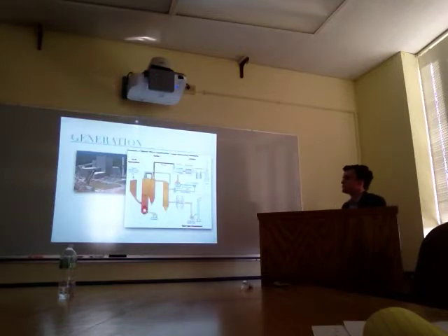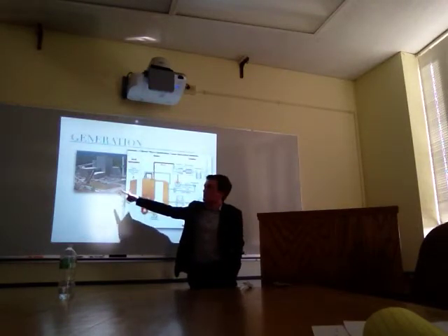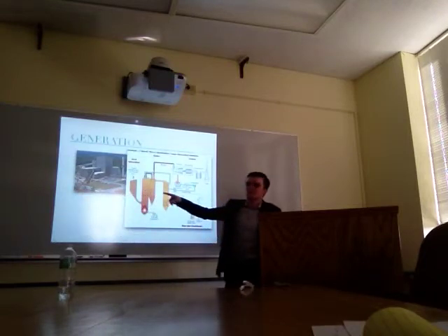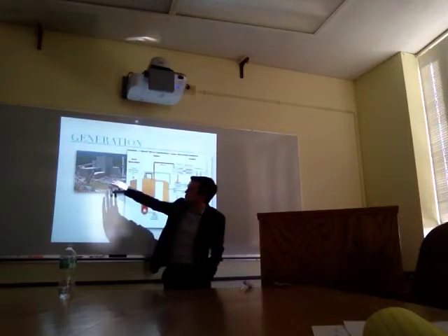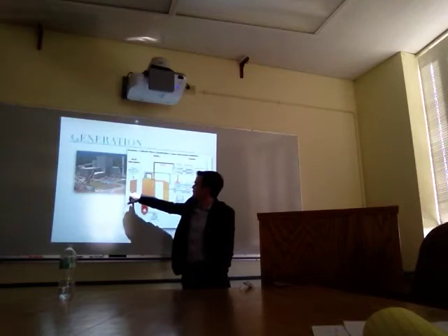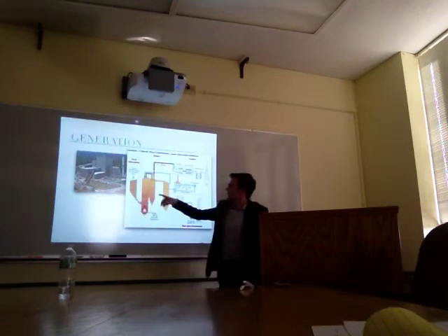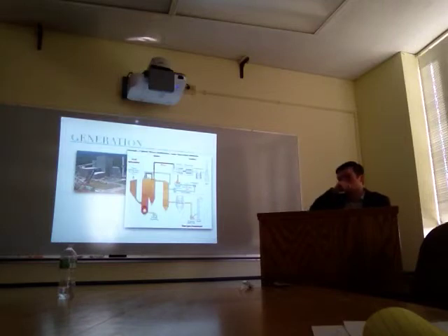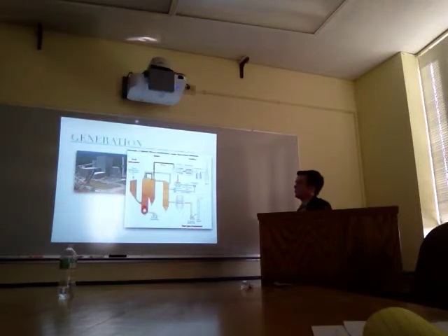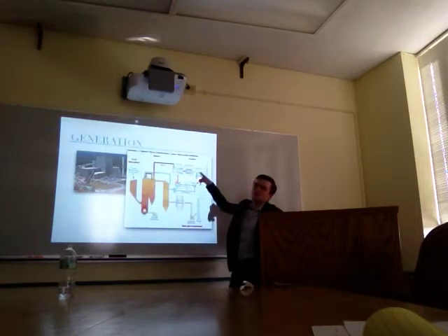This is an example of essentially how power is generated from biomass. This is the Sherman Wheelabrator plant, which is where I grew up, and my dad worked there. We're going to talk about that as more of a hands-on example in a moment. But this picture matches up pretty much with the process. The fuel comes in here, that's this belt here, and feeds up into the boiler. The boiler heats the water source. Most power plants were built right on a river or a stream of some sort, which is where they get their water. That water source creates steam when it evaporates, turns a turbine, turns a generator, and creates electricity.